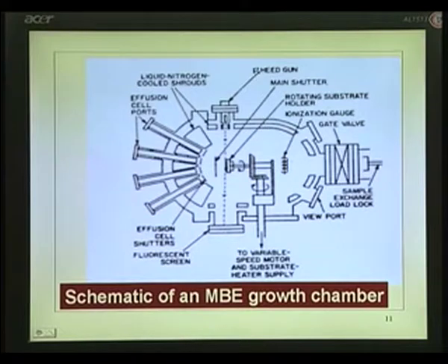So, not only is this whole chamber made up of steel, so that it does not degas, okay, between these two you will also have the gaskets, because after all you can't bring two surfaces like this and keep them vacuum tight. A slightly soft material is used as gasket, they are actually made up of metal, gold, which I mentioned yesterday.